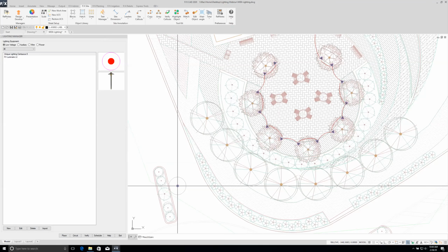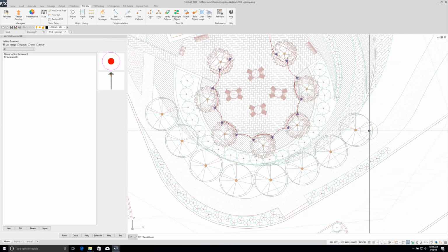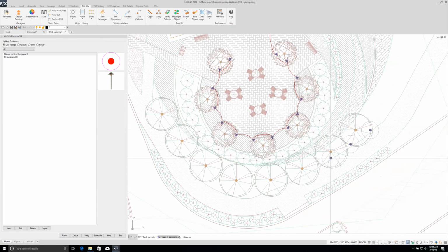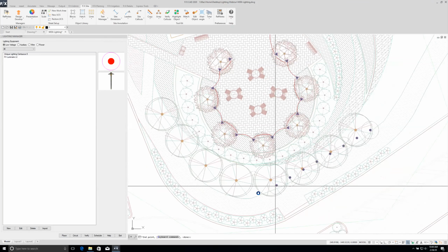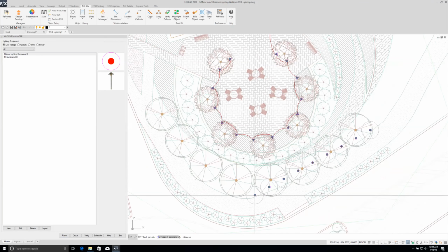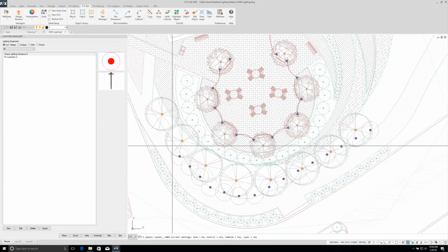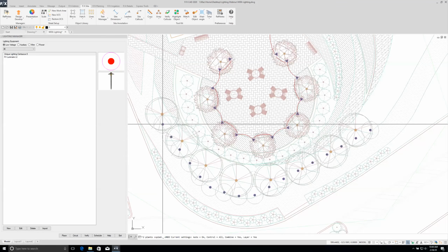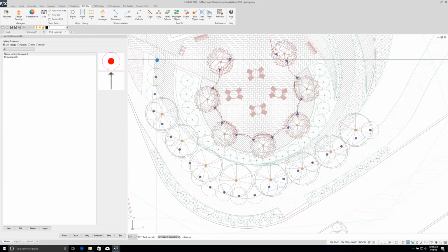There we go. That is a more appropriate footprint. So now let's place a couple of these along the path. And I'm just going to do copy long line and be quick about it. Right now I'm using the S key to change the fitting size. And I probably want these to overlap a bit. And just continue drawing my fixtures up till I have good coverage along this path. Perhaps to there.